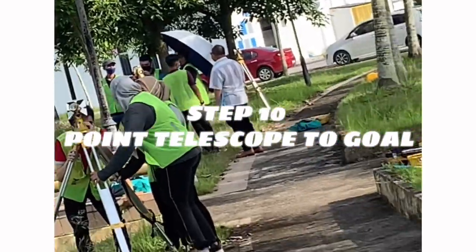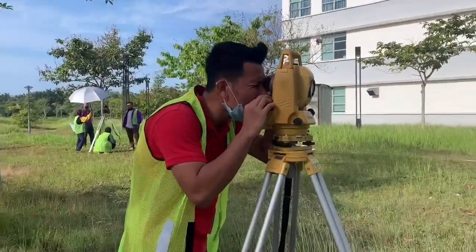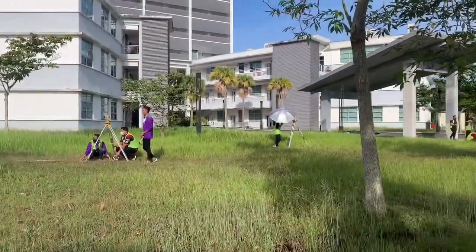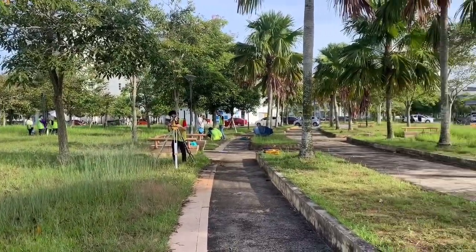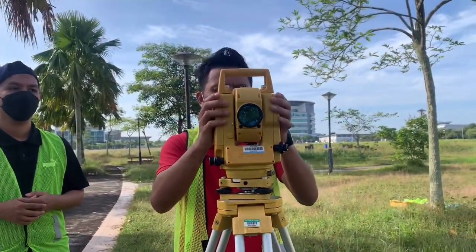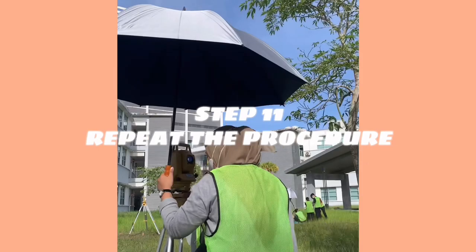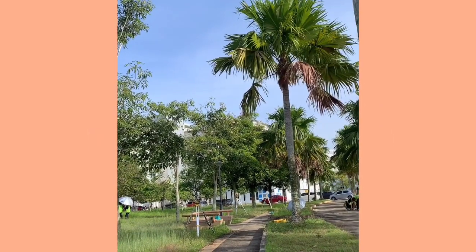Step 10. Point the telescope to the target. Release the horizontal and vertical clamps and point the telescope to a featureless background. Adjust the reticle focus adjustment until the reticle image is sharply focused. Point the telescope to the target and regulate the focus ring until the target is focused. Step 11. Repeat the procedure. Repeat the procedure at the prism setup and stations 1 and 3.